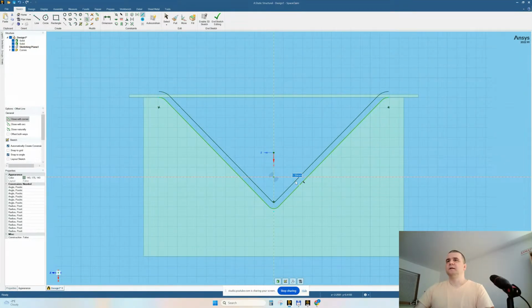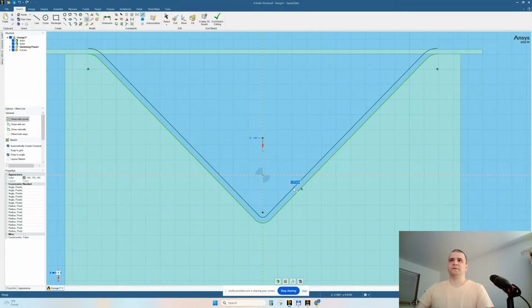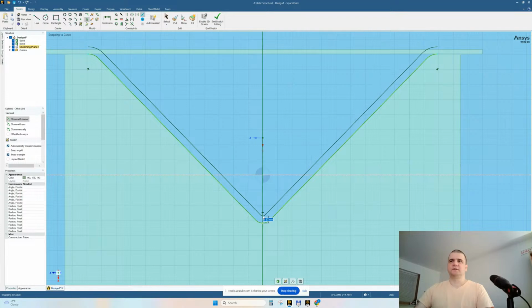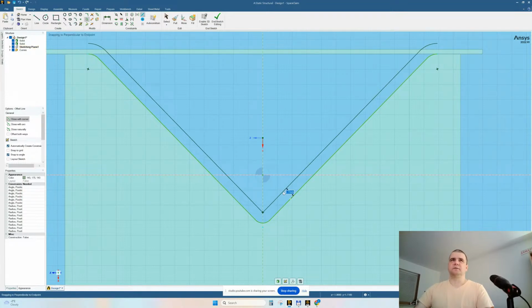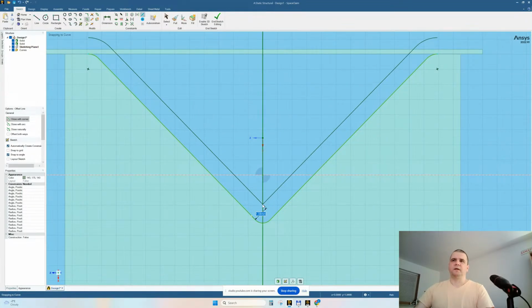Look here, yes? So when I was searching for the radius, I took this into account. And I left it as thickness, I left it 0.3, if you remember at the beginning. The thickness is 0.3. 0.3 ensures that here we have a radius. If I was to make a higher thickness, 0.7, then it would have mandatory been a pointing or a very sharp edge here.